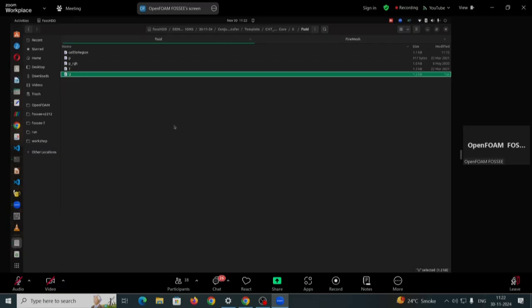Basically, whenever you have the effect of buoyancy or gravity in flows, the pressure due to buoyancy will be different. If you move along, like if there is elevation, or if there is multi-phase flow due to density, the total pressure will be different. The hydrostatic pressure will be different. If you remove that hydrostatic pressure, then you will have kind of one single pressure system for the domain.